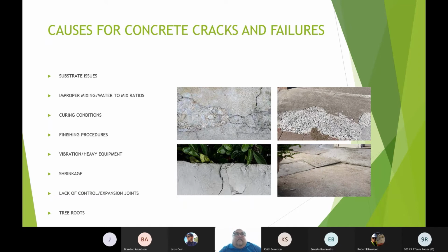Plastic consistency is pretty close to oatmeal cookie dough, chocolate chip cookie dough at most. It has a stiff consistency to it. Yet once you start working the material with the proper tools and you're working it like it should be worked, it actually becomes more workable. Things that are going to affect that workability are the water content, and also the conditions outside. It's really hot, if you've got hot water in it, if you've got cold water in it.